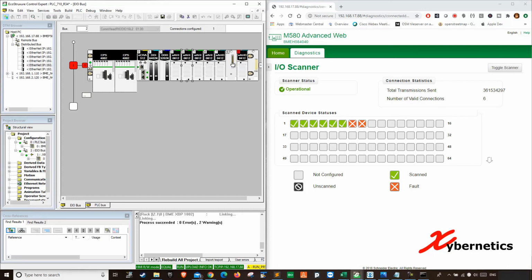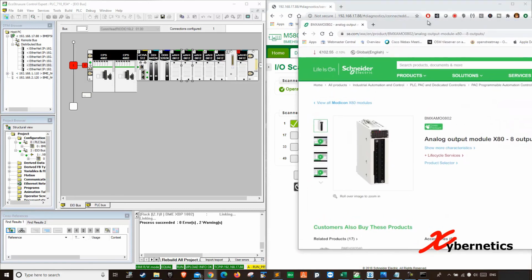So yeah, I had those problems, and like I said, if you don't really need that HART configuration, I would recommend you go with that 4 to 20 milliamp only AO card, like this guy here, right?